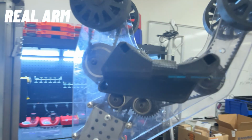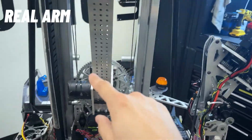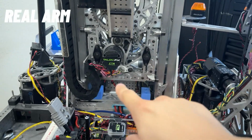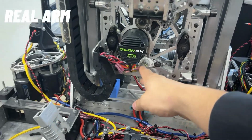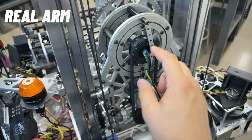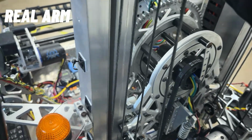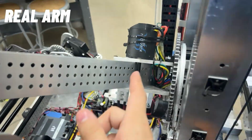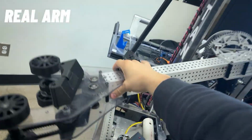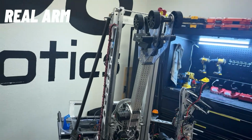At its core, it runs a high gear reduction with a motor packaged inside the arm tube. All of this is driven by a custom 10 DP tooth gear plate, rotated by a very high gear ratio paired with a Kraken 60. We also have an absolute encoder on a 1-to-1 pulley ratio that guarantees we know the exact arm position at all times. We also have a slip ring which allows continuous rotation without hesitation. That's hooked up to our claw motor. This was definitely the hardest subsystem to get right and the most rewarding to solve. It sharpened my approach to design, and with that, I moved on to the next design.